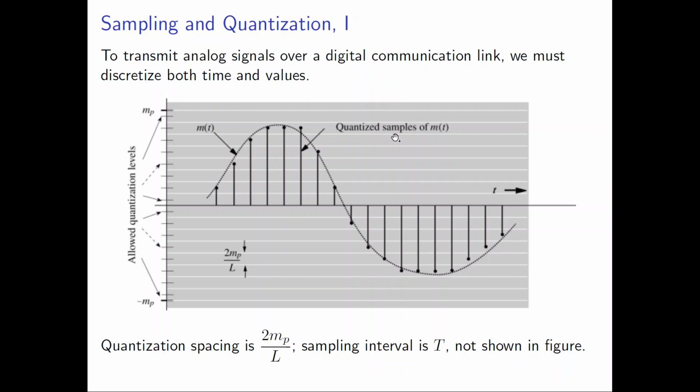Quantization divides your signal in amplitude. So basically, you divide your signal in 2 dimensions, time and amplitude. The division of your signal in time depends on the sampling frequency and the frequency of the signal. The higher the frequency, the shorter the spacing between these samples.